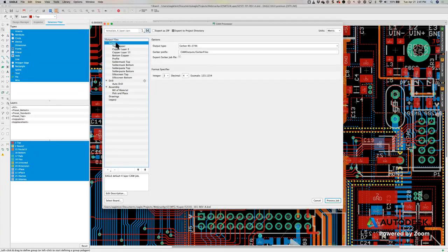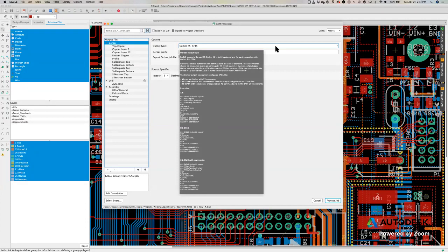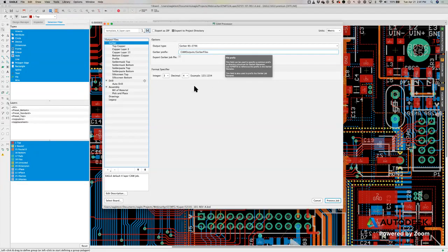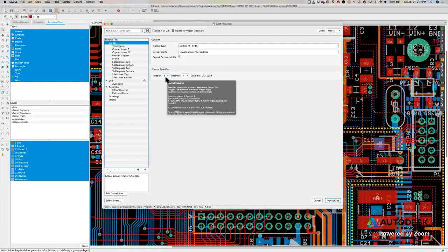If you go to where the setup to generate all this is, the setup header right here, you notice that we're using Gerber 274X. We do support X2, but we've had really good luck with Gerber 274X. Board houses kind of prefer it, but we do have X2. It's letting you know what the prefix is going to be and what the format specifier is. By default, if I'm not mistaken, we actually use 3.4. So 3 digits for the integer and 4 for decimal points.